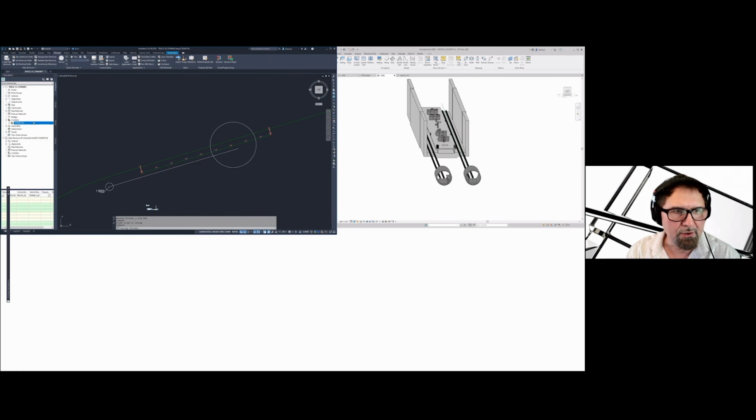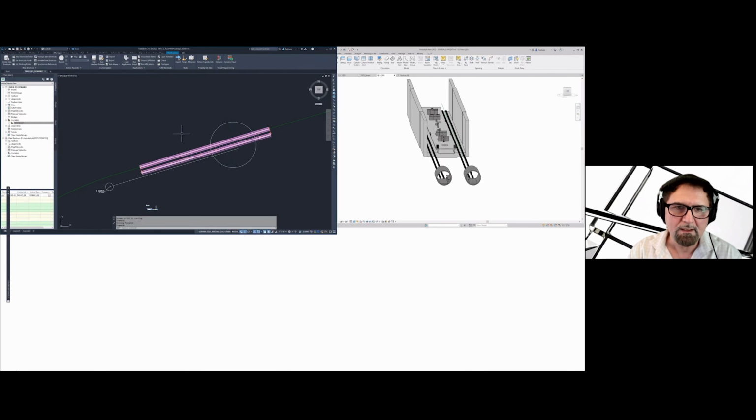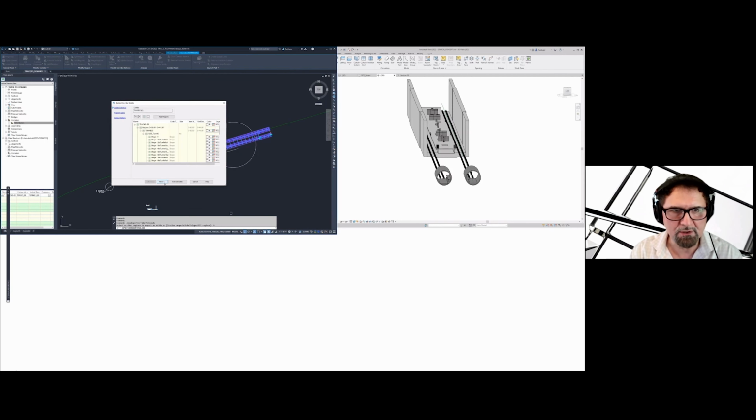So as you all know, in Civil 3D, corridors, once calculated, can be extracted to solids. And I'm going to extract solids from this corridor model using all of the regions that are there, only 3.